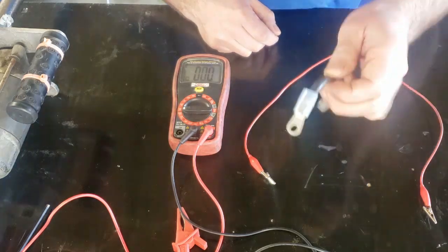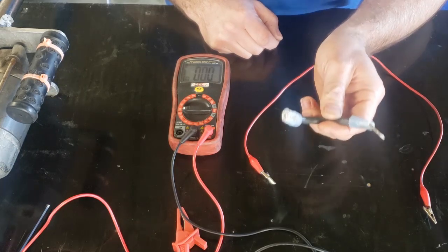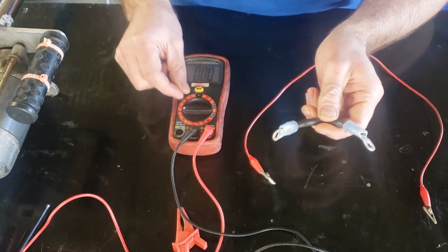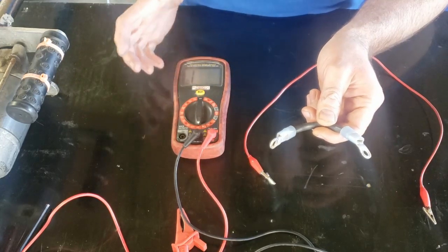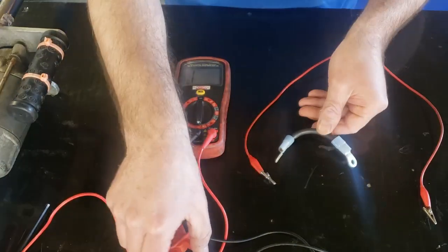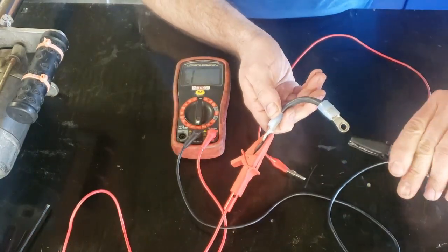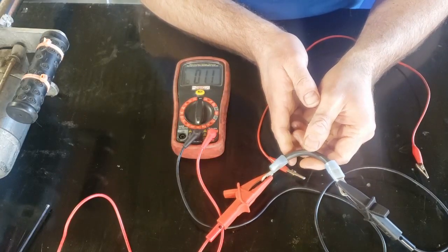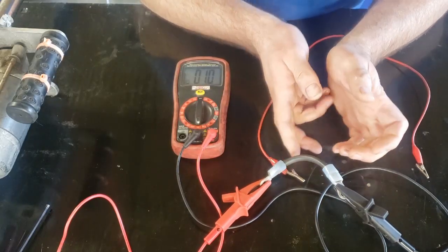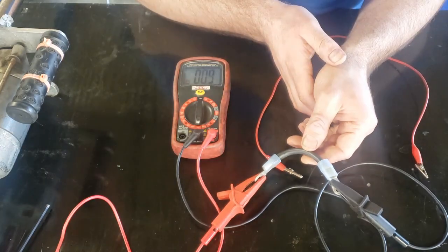So we have 2 wires here. This was the healthy battery cable that was being used in the last demonstration. And I'm going to go ahead and measure the resistance across this. So I'm going to go down to my ohm scale, and I'm going to set my scale on 200 ohms. And when I put my leads across the ends of this wire, I find out that this wire has approximately 1.0 ohms across it. All right, so there's 1 ohm of resistance through this cable.